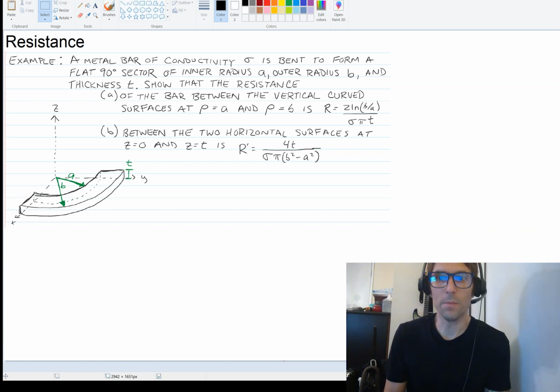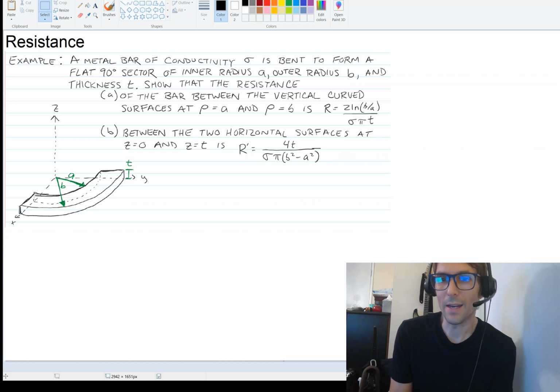Hey, welcome back everyone. In this video we're going to take a close look at resistance. Now we previously calculated resistance and we looked at resistance when we started talking about conductors. But when we calculated resistance, we only calculated the resistance when we had an object that was uniform in cross-sectional area. And here we're going to look at non-uniform cross-sectional areas, how we can apply Laplace's equation to figure out the resistance of such an object.